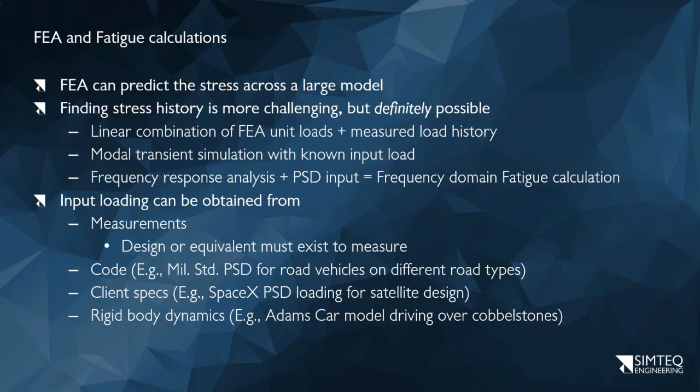For normal road vehicles, I think each of the automotive manufacturers will have their own specifications. We also have client specifications sometimes. I know SpaceX and NASA and all of those. If you want to supply a satellite that they have to launch for you, you have to do a couple of tests, and some of them will be you apply PSD in the X, the Y, and Z direction, which they specify. Those PSDs come from the vibration and noise characteristics of the launchers that they've measured